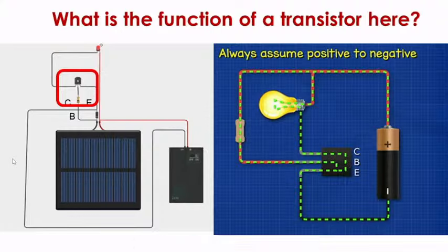When you get this lamp into the shadow or dark, what will happen is there is the least resistance. Least resistance means more current. So the base will get more current and this line will also open. That means the LED will turn on. So in the night, this LED will turn on automatically, provided that this battery is also charged. This solar panel helps in getting this rechargeable battery charged.